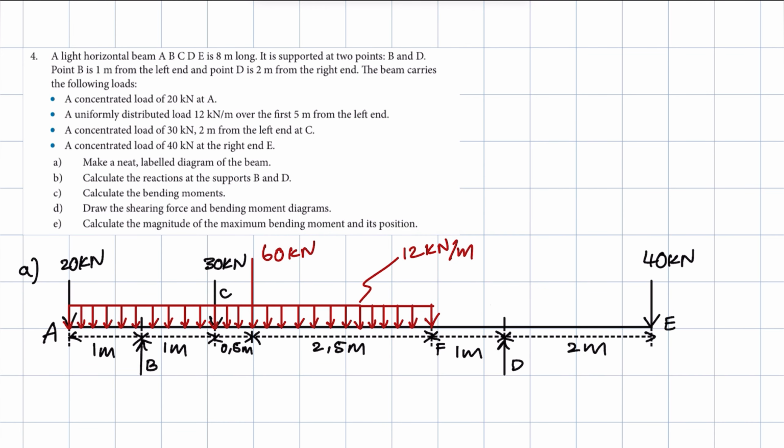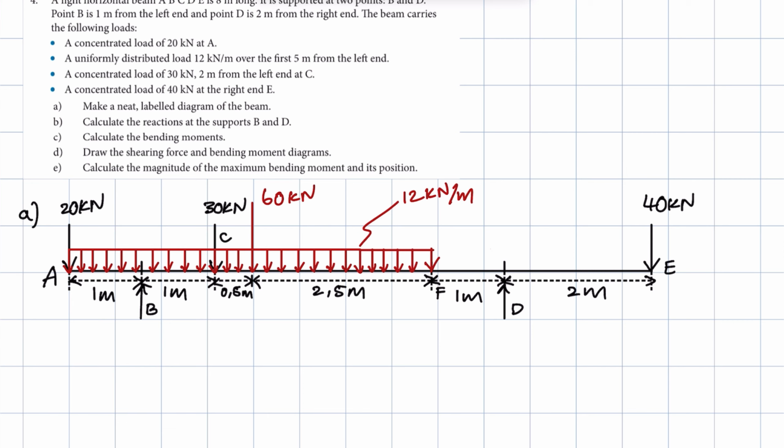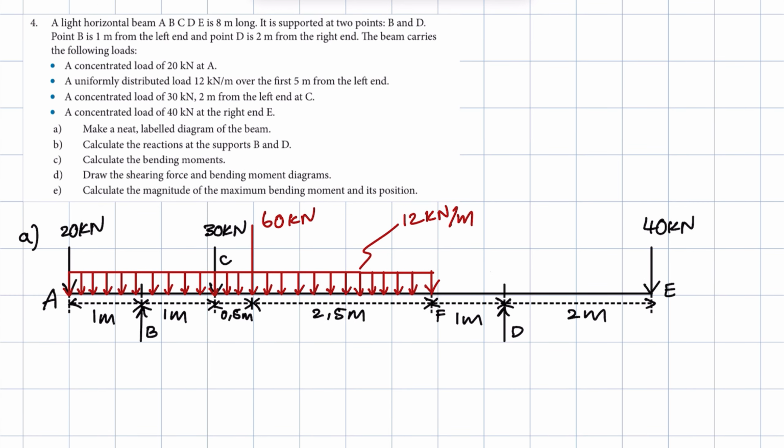Now I've drawn the beam and shown all the points on the beam, as well as all the concentrated loads and the reactions at the supports. I've shown all the important information. As you see, the measurements are such that they are convenient for calculating reactions at the supports. So always draw the beam and write down the measurements in a way that is convenient.